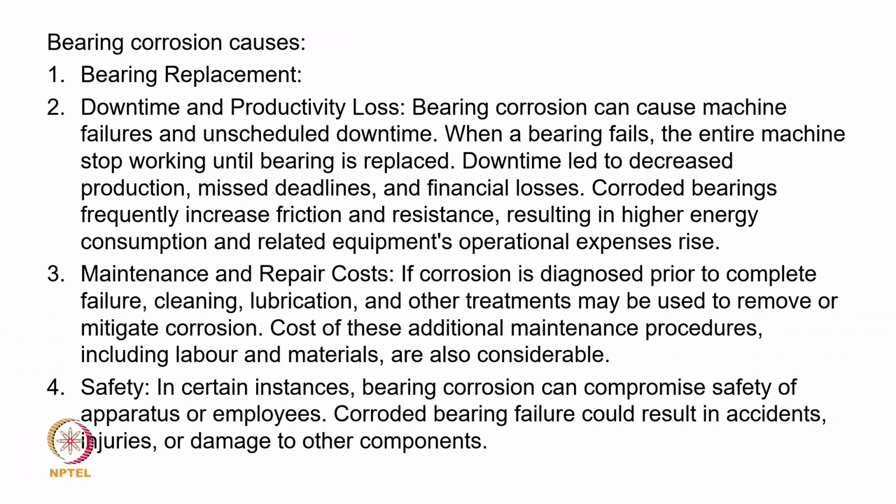And moreover, not only this, even in the starting condition, the bearing is getting corroded because of water ingress, or maybe some other acid formation or some gases. What will happen in this situation? A corroded bearing will increase the friction, because we know the dimensions are changing. Naturally, when the dimensions are changing, some sort of resistance will be there. It will increase the friction force. That will cause high energy consumption, and then it will increase the operational expenses also. Again, if we go for more frequent maintenance, the labor cost will be there, and the oil change and other associated parameters will also increase the cost.